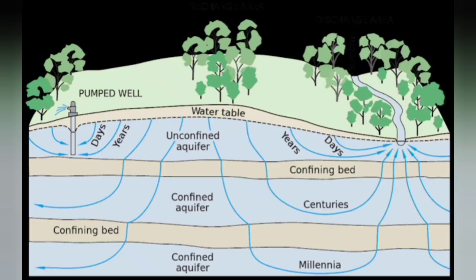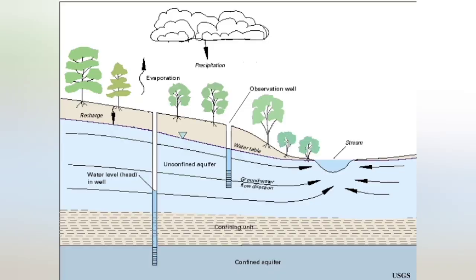So in the planning we have discussed the hydrometeorological studies and hydrological studies. Now we will discuss the soil infiltration studies. In case of artificial recharge through water spreading methods, soil and land use conditions which control the rate of infiltration and the downward percolation of water applied on the surface of the soil assume special importance.